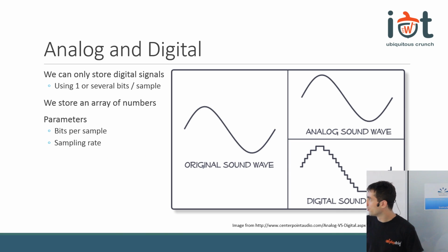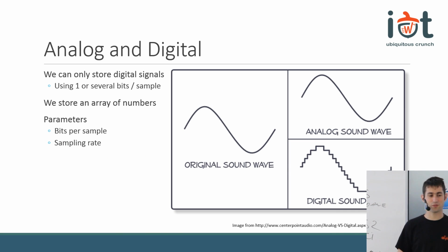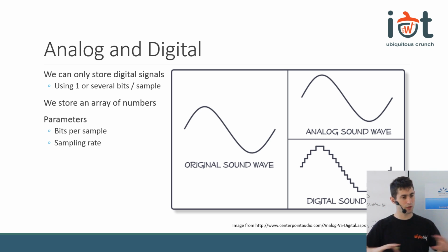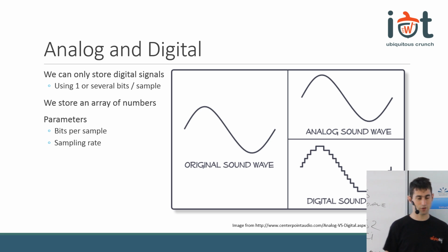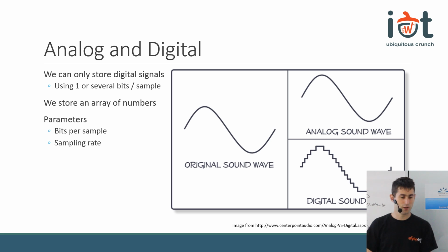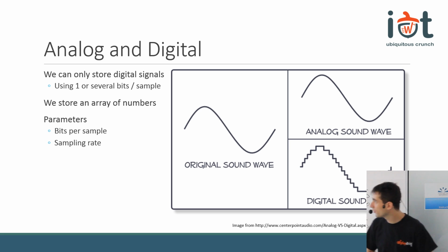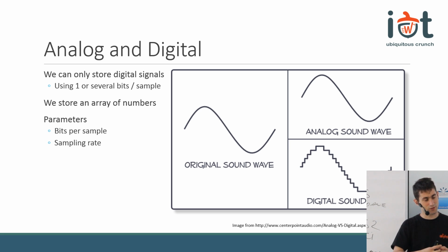Okay. So basically, there are two types of signals, analog and digital. The thing is that everything in the environment is analog. So absolutely everything is actually continuous and analog. In order to use the information from the environment, we need digital signals. And basically, a digital signal is a stream of numbers. It can be either 1 and 0, or it can have different values. So it's a misconception that digital signals are only 1 and 0.